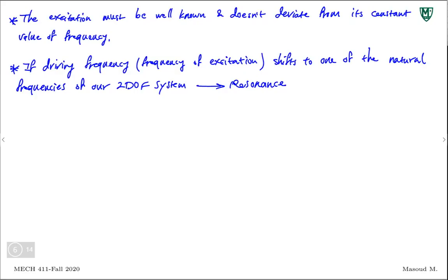Something else you have to keep in mind is that this is the case of zero damping. We designed this absorber for zero damping. Now, if there is damping, the magnitude wouldn't be zero. Right? This assumption was based on no damping. We said, well, if there is no damping, this is the x, make the x equal to 0. This is the frequency. So if your excitation frequency is equal to the natural frequency of your absorber, zero displacement. But that's the case for no damping. If there is damping, just keep that in mind: you don't get zero magnitude displacement for your primary structure, as they call it, primary mass, or main structure.